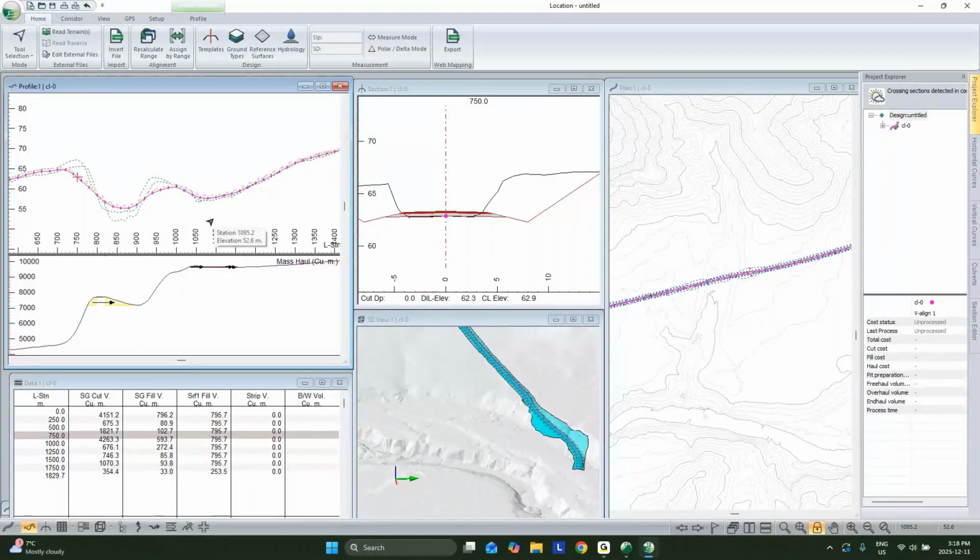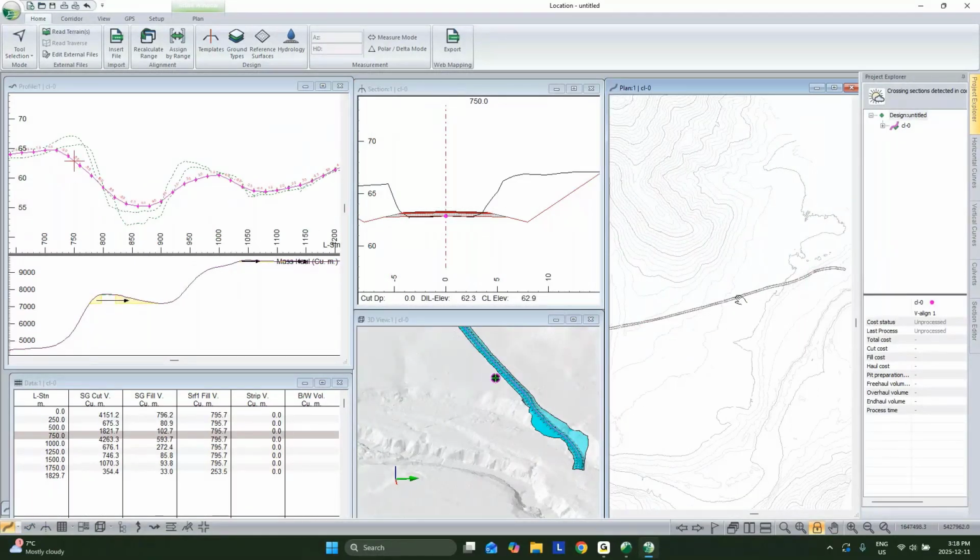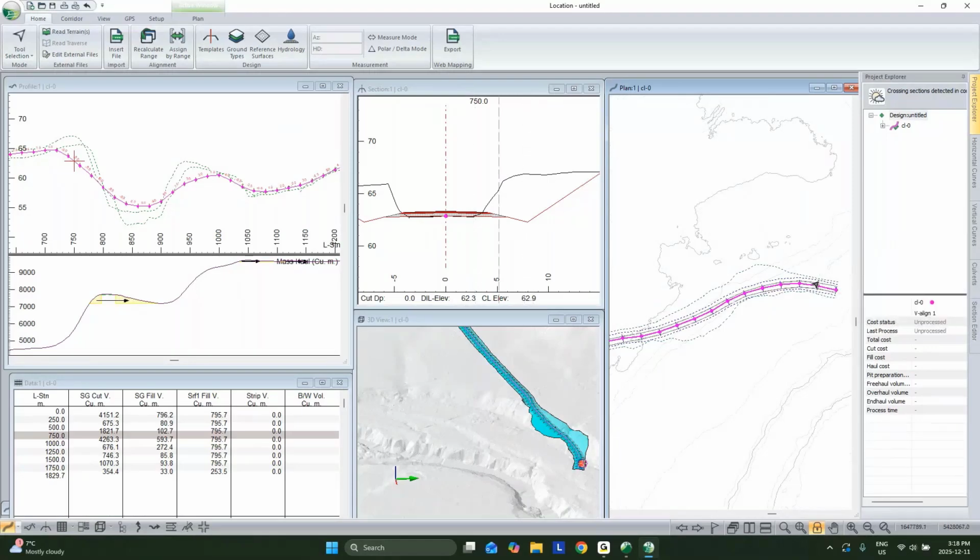Now, if we're looking at this critically as well, I've got some pretty tight vertical curves here. I'm not sure what my horizontal alignment's doing in terms of the radius that we're using on the alignment. But if we wanted to keep this as a pure overlay and widening project and not do any realigning and not really assess the geometry that we have, we could stop here, maybe throw in a few pipes, go to our documentation, and we've got a model. But it would be an awfully short webinar if we did that.